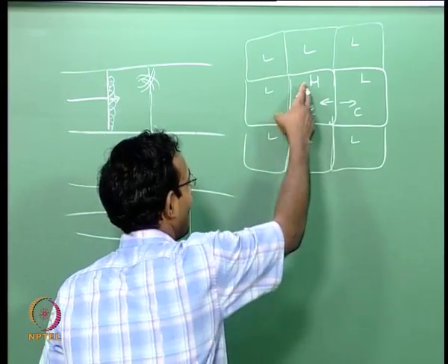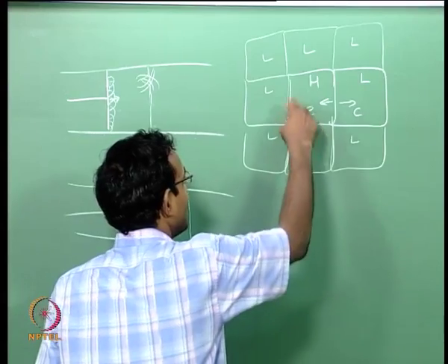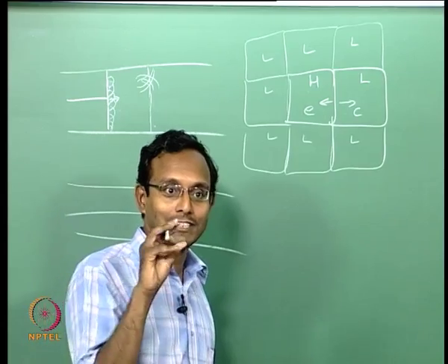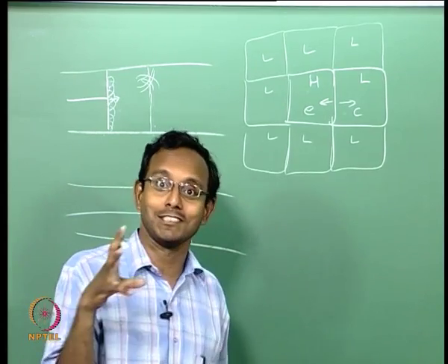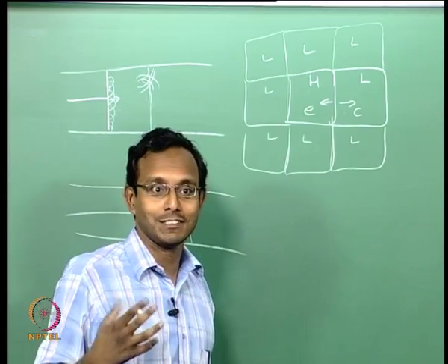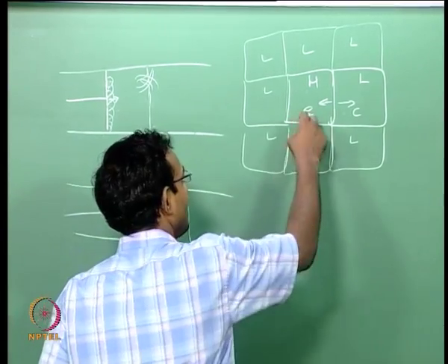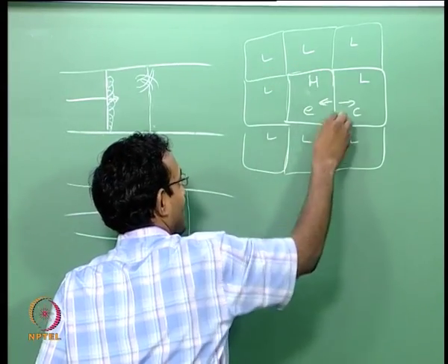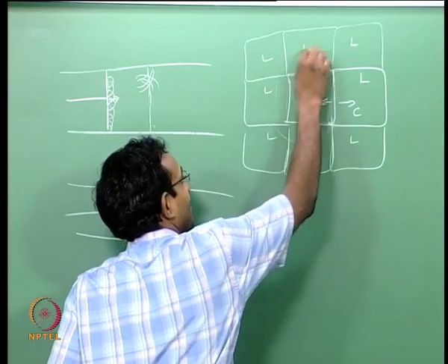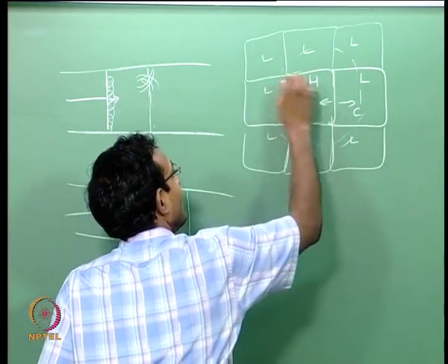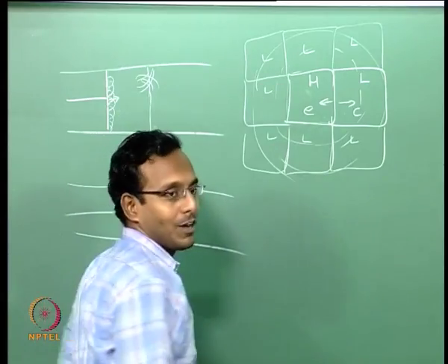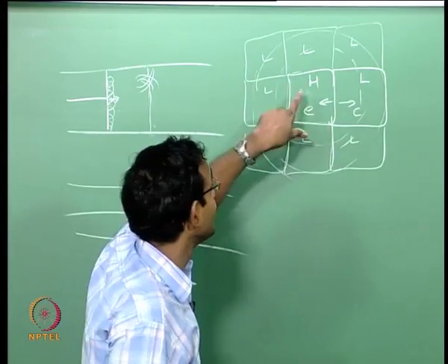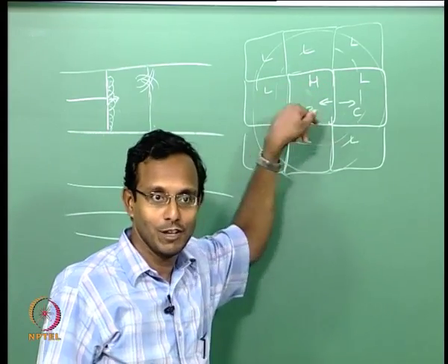If there is a bomb exploding here, then this fluid element experiences very high pressure. Why? Sudden release of energy, huge pressure, all that solid inside the bomb is now gas, they all vaporized, they need space, so it pushes out everything. That is your expansion, the compression created from here, this high pressure region which is now going to expand and form compression waves all around. Okay. And while the compression is going out, expansion is going in from all directions, which is decreasing the pressure at the center. That will also happen.